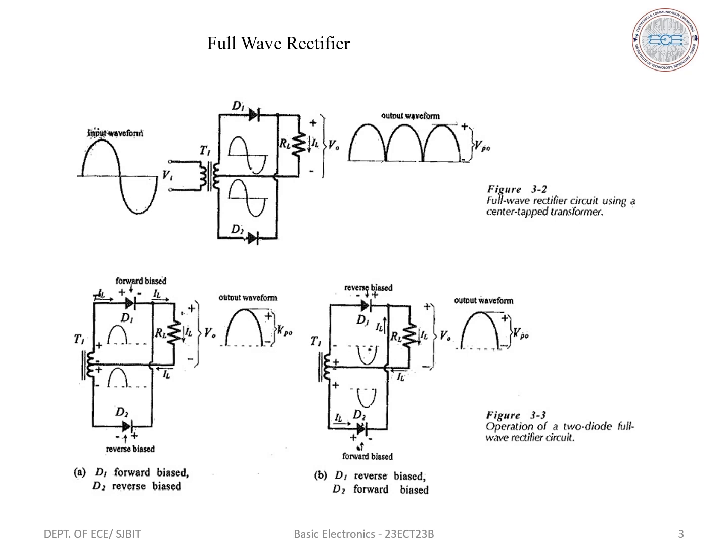The time required for C1 to charge to the maximum level is determined by the charging circuit time constant. The time required for C1 to discharge is more. The discharge time constant is determined by the capacitance value and the load resistance RL here. The figure shows the voltage waveform for the biphase rectifier with and without the capacitor present.